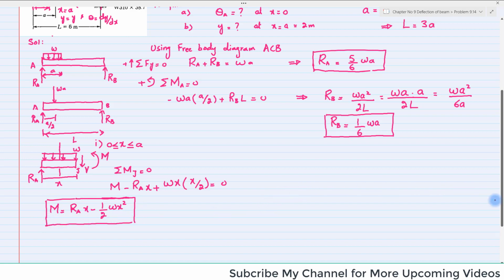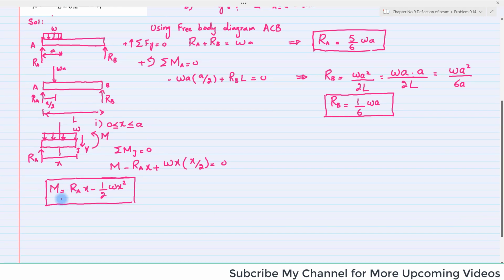Now you will have to apply the equation EI d square y over dx square is equal to M, and this moment is equal to RA into x minus 1 over 2 W x square. Clear?